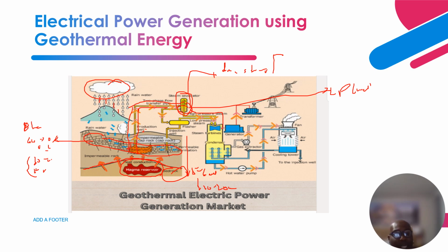So the wet steam collects below and flows back here, where it flashes, and creates a low pressure steam that flows to the low pressure section of the steam turbine, right? And sometimes, to get it a little bit drier, depending on the geothermal energy configuration, it goes through some reheating before it comes into the low pressure section of the steam turbine, right?